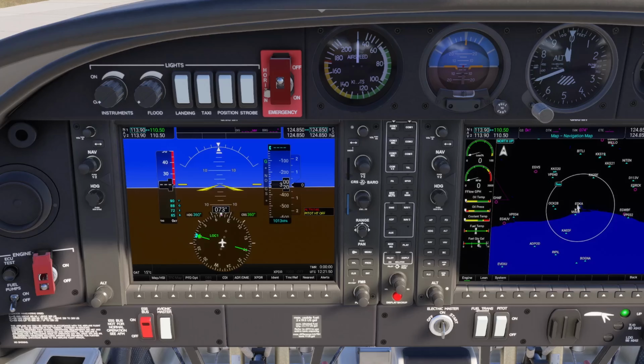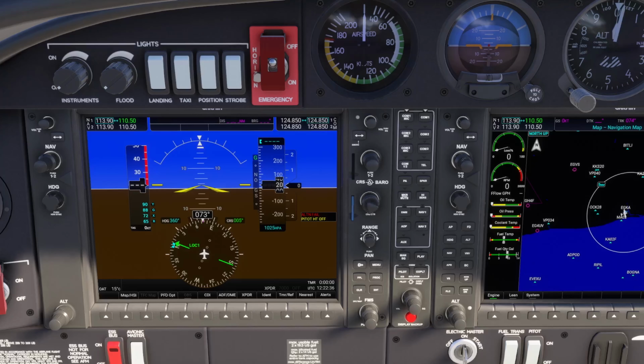As I'm offline for today's flight, we won't do that, but pretend we have put the frequencies in there. So listen to our information and pretend we got information Alpha and QNH 1025. You set that via the outer knob here, as you can see.